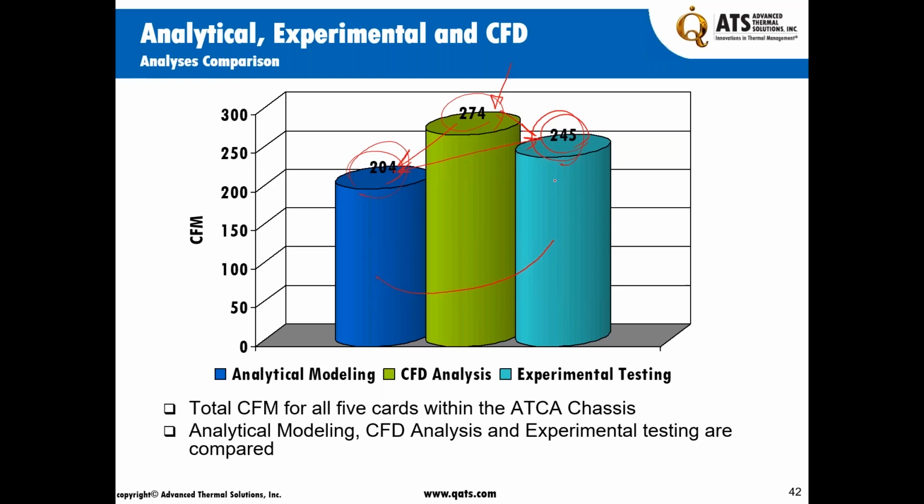And notice one thing that we did not do. We did not do the measurements here and then take that information, put it into our CFD model, so that now we know exactly what the inlet velocity is, and then simulation and CFD come in within like 2 or 3% of each other. That's a no-no. The solutions have to be independent. That means I do, say, the analytical modeling, you do the experimentation independent of me. We come together to the table. Maximum we have to be within 20%, and we are almost there in here. But the computation and the experimentation are much closer. So you can see the benefit of it.